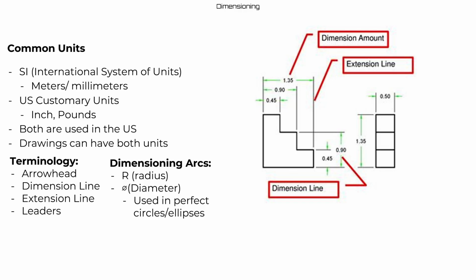Our dimension line, which are the green arrows pointing outward. So our arrowhead is pointing inward, but our dimension line is pointing outward. So it basically states where the dimension starts and where it's going to end. Extension lines. We use extension lines when we usually don't have our dimensions inside the part. So we usually have an extension line so that the dimension can be seen, and also where the limits of and also where the dimensions are going to be lined up.